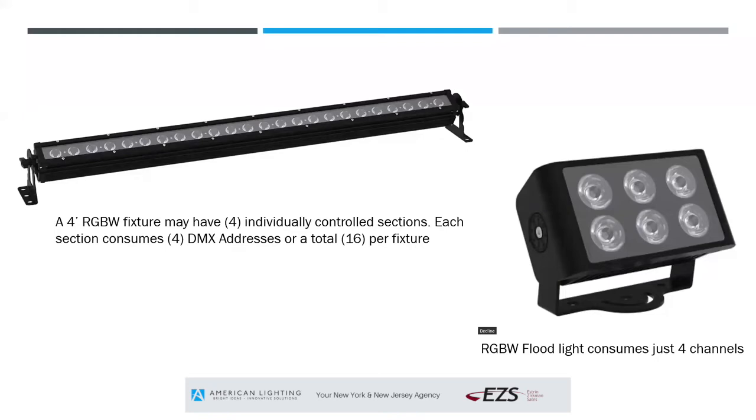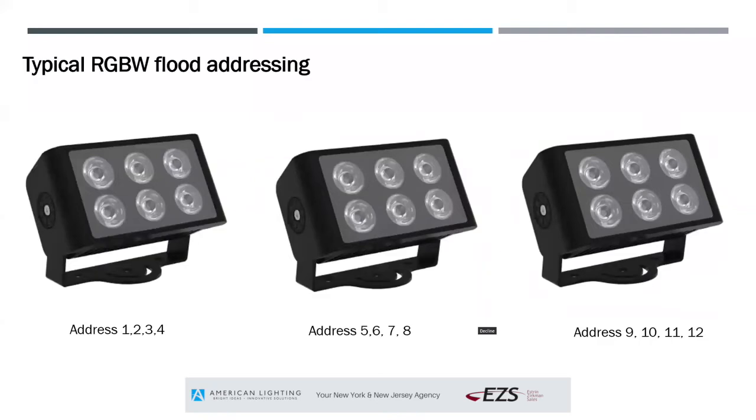A typical RGB flood, though, will be 3 or 4 addresses. If we're talking about an RGBW fixture, a typical flood type fixture will have just 4 addresses. So typical addressing, if we're doing a building on the exterior and we want each one of those fixtures to be controlled independently to do a different color, the first fixture would start at 1 and it would consume 1, 2, 3, 4.